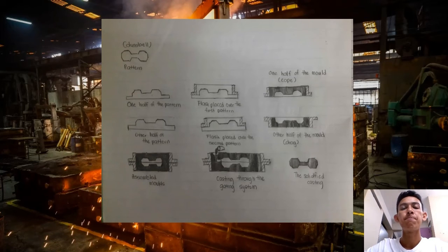The next one is when the desired final material is melted in a furnace and is then poured into the mold. It is carefully poured into the sprue of the mold, as we can see here, where the molten metal will conform to the cavity left by the patterns and then left to cool completely. After the metal is no longer hot, manufacturers will remove the sand from the mold with many methods such as vibrations, water jets, and other non-destructive means, which we call it as shakeout, to reveal the rough final part.